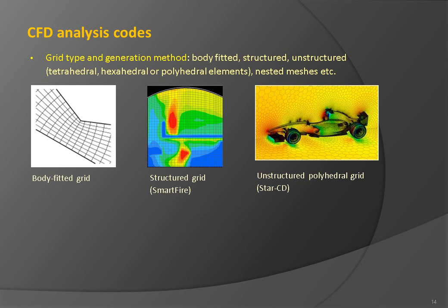In general, a numerical grid can be structured, as in FDS or KFX, or unstructured, as in ANSYS or STAR-CD. Structured numerical grids offer much faster simulations and less complexity in the implementation of CFD models, but on the other hand, fundamentally less flexibility in modeling geometrically complex forms.